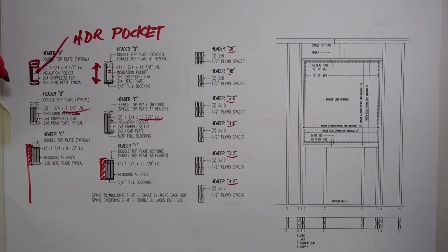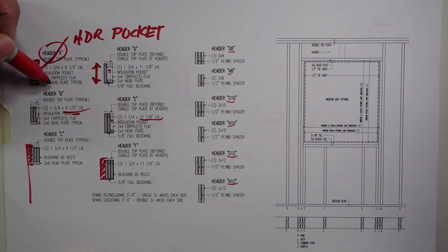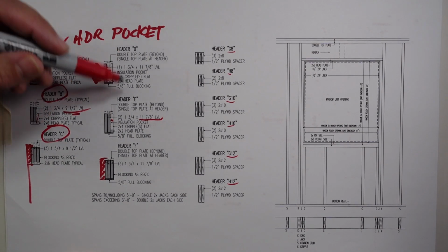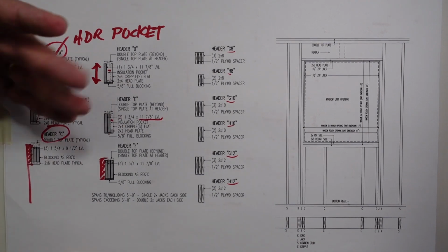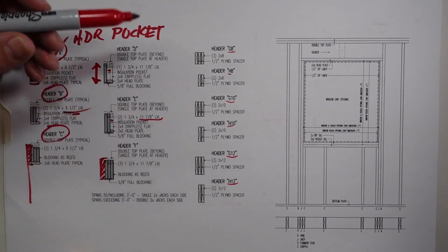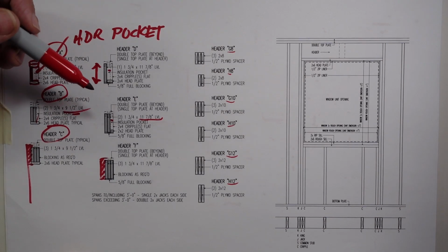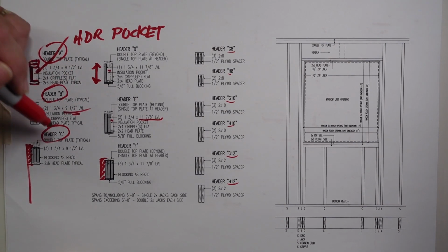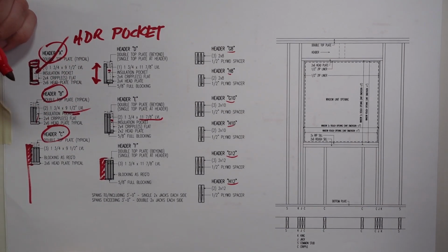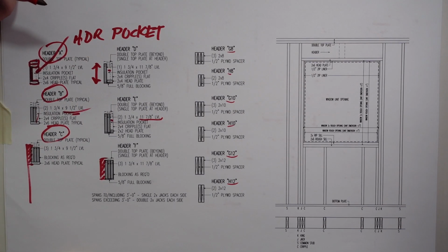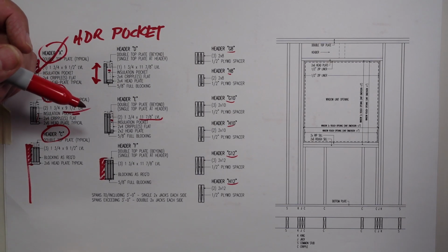But then anywhere, I just simply refer to header A, B, C, D, E, F, or if we need to create a new one, sometimes we'll make a larger one. But if it's a one condition, sometimes I'll just write it out on the drawings, but we'll just drop those in on our framing plans, and then the framer can refer to the header schedule here and reference that.